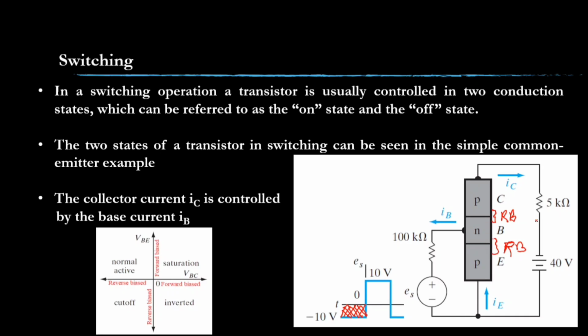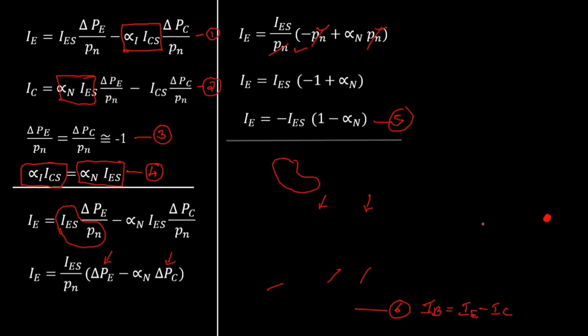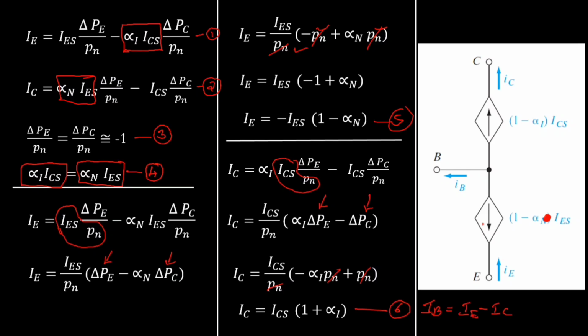So whatever voltage is applied at this point is going to drop across the BJT. Almost 0 voltage will be across the 5K resistor; it is almost literally open. So whatever you apply, you can read across the BJT. That means if you connect a voltmeter across these two points, you can read 40 volts across the BJT. That is the actual meaning of the BJT in cutoff state.